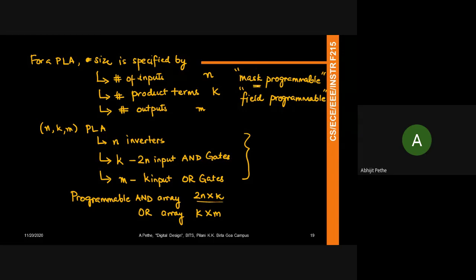So the chip, when you get it from the foundry in the case of a mask programmable array, already has the programming done onto it, right? When you buy a mask programmable chip, the programming is already done because you would have contacted the foundry prior to getting the chip in your hands. Whereas a field programmable array is programmed outside, when you buy the chip and then program it electrically in the lab. So you'll see these words if you start looking into whether it's mask programmable or field programmable. And field programmable are generally used because there you don't have to deal with the foundry.